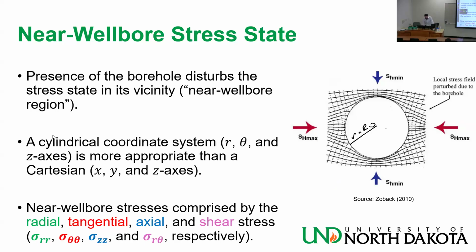Now I'm going to go exactly at R equals RW, and I will look at the stresses there on the edge of the wellbore. I'm going to have a radial stress, and I'm going to draw it in the tensile direction, just because I want it to look nice on the plot. That doesn't mean that it is. Don't worry about where the arrow is pointing, because if you calculate a positive value, it's pointing this way.